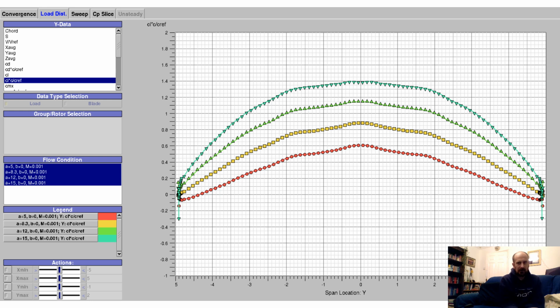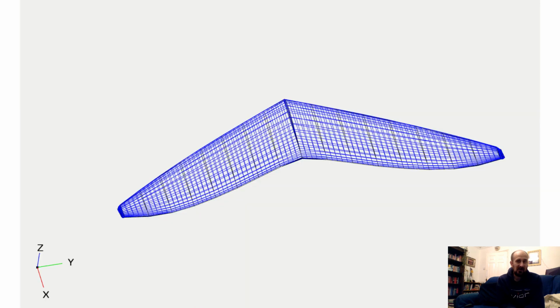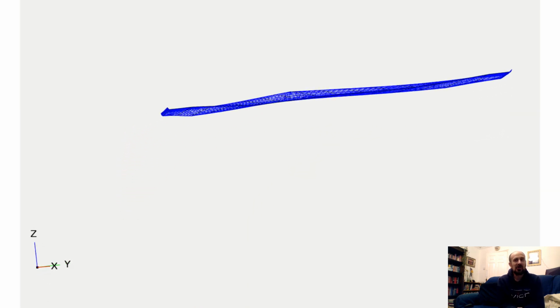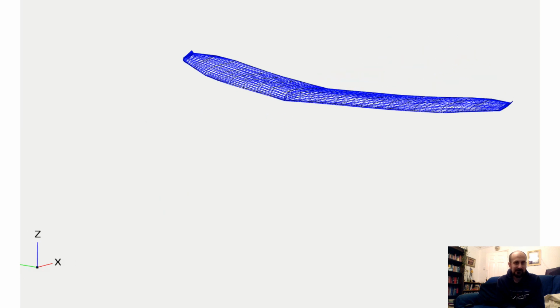Now, as I say, this data is generated for the Puma geometry, but it's typical of really any hang glider, especially any sort of high performance hang glider, would have a very similar lift distribution to that. I.e., no hang glider is getting really anywhere close to an elliptical lift distribution, even with the VG pulled really tight. So the question is, why has no one done this yet?